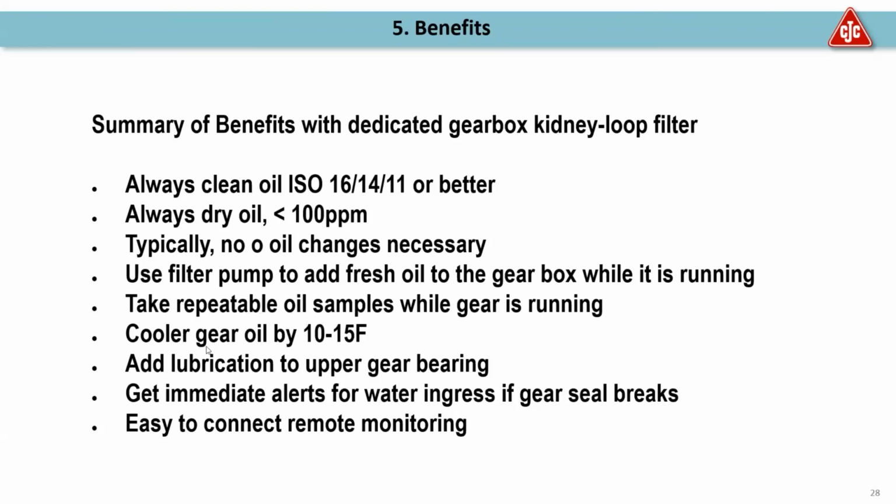Your oil is generally cooler by about 10 to 15 degrees Fahrenheit, just because you are circulating that oil out of the gearbox through the filter and back into the gearbox. Yes, you can add the lubrication to the upper gear bearing if that gearbox is equipped with another connection on top. You can get immediate alerts for water ingress if the gear seal breaks.